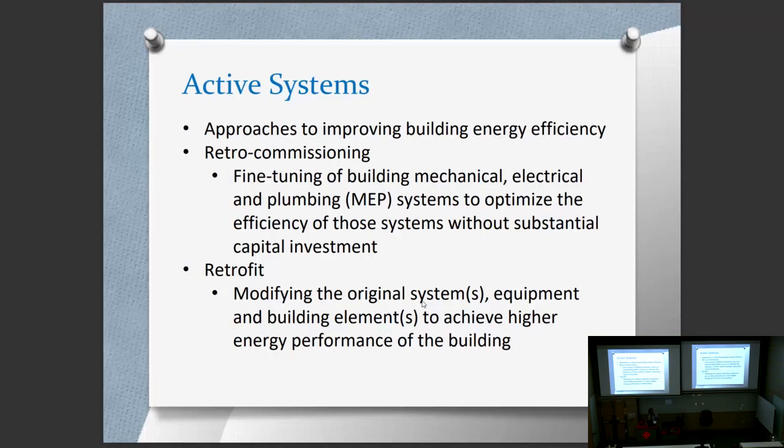For the active system, it would be about the building services system. So, approaches to improving building energy efficiency: we have different kinds of energy efficient equipment, like using LED, task ambient lighting, asking the occupants to switch off the lighting, or some automatic lighting control, or maybe variable speed pumps, district cooling, chilled beam air conditioning, high volume low speed fans, and regenerative lifts.